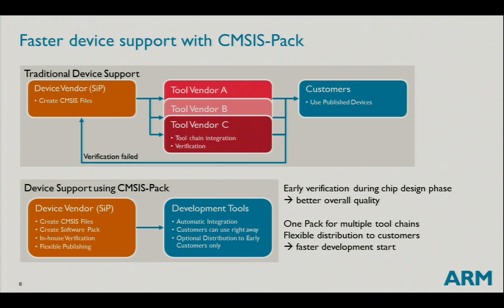With the CMSIS-Packs, it's much faster. During the device development, the hardware development, the silicon vendor can already provide the required drivers, required startup code, pack everything in the pack, test it internally, and then on the very same day they announce the new device, they can publish this pack, and the device support comes immediately.